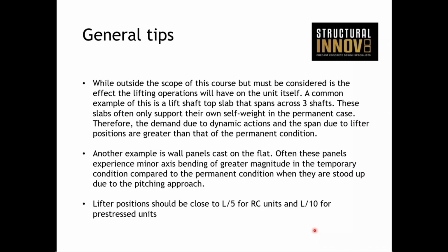And also another example would be pitching walls and pitching columns. When you're tilting those up, they haven't been designed in the permanent case for that effect, particularly if you're pitching around the shallower axis, the thin section, like with this example here. So just bear that in mind, and make sure that's looked after.